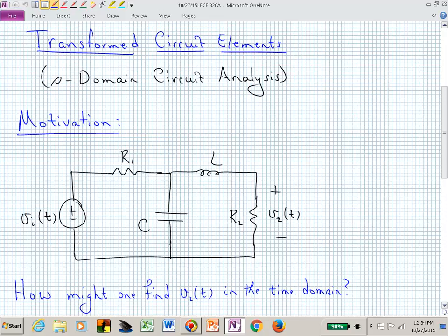And those resistors do what? They absorb energy. And if we just had the L and the C, then you might have a pure oscillator. You would have a pure oscillator if you just had L's and C's and no resistance. But physically, you're going to have some resistance even in the L and the C themselves as a circuit element. But here, the L and the C might put you on the imaginary axis. The R's put you in to have damping. This is a passive circuit that's stable.